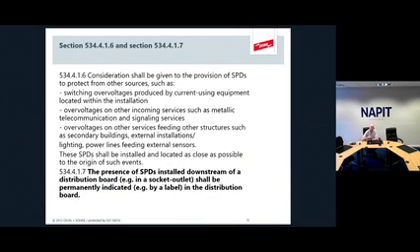There's a couple of other regs which are interested in this part, and you have to think about those overvoltages generated within the installation, and you also have to think about surges coming in other services. So it's all very well having it on the low voltage mains input, but what if you've got an overhead telephone line? What if you've got a satellite dish on the roof? They're all other services coming from the outside in, so you have to consider those as well.